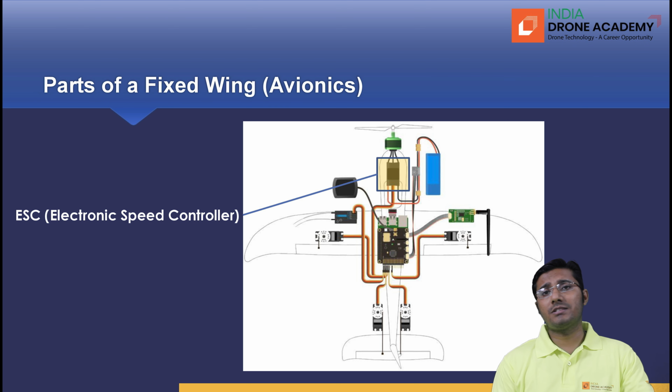The brushless DC motor has a rotor and a stator. The brushless DC motor, which is of the outer runner type, has a rotor outside frame that rotates, and inside there is a stator that has coils, or you can say poles. So the electronic speed controller identifies the location of the rotor's pole, and then it energizes the poles which are part of the stator, and that helps the motor to generate torque. This is how a BLDC motor works.